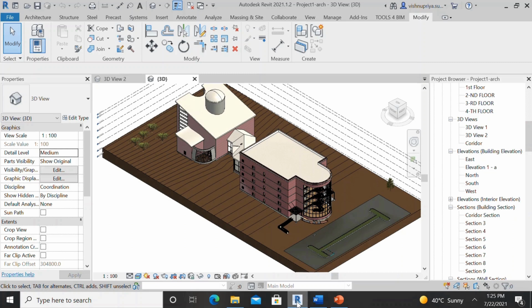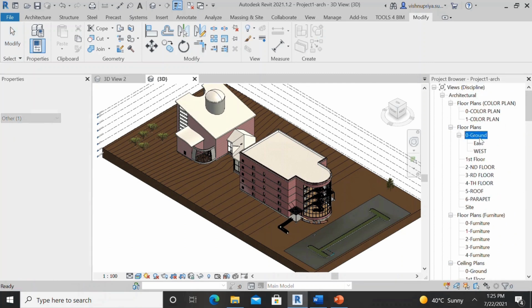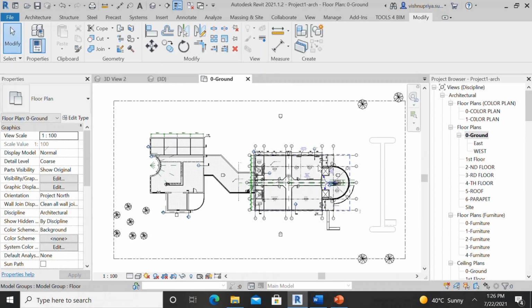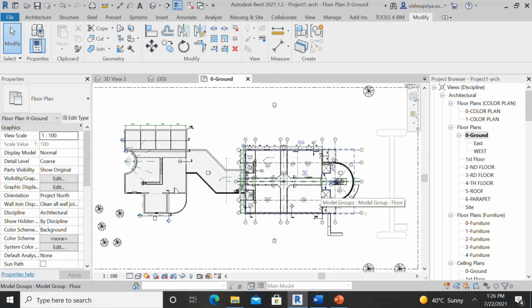But in this case, the problem in CAD is, suppose I take you into the floor plans. See here, we created a floor plan. Then if you wanted to see a section here, you separately created the sections. You imagine how the section will look, then you create it. Later on you decide you need to see a cross section somewhere else, meaning you need to create it again.